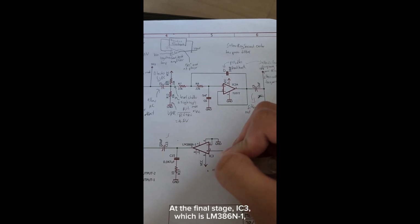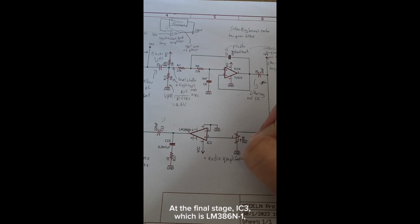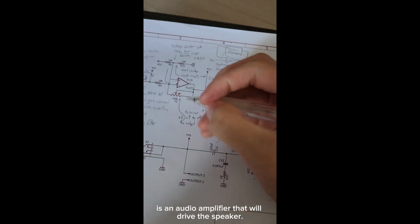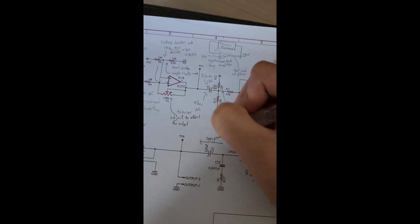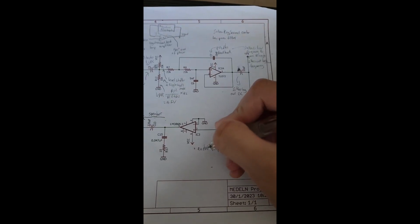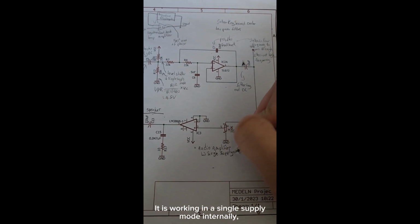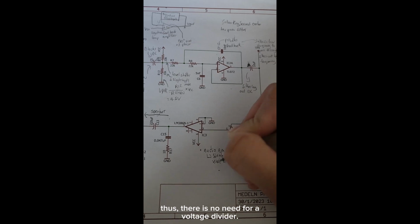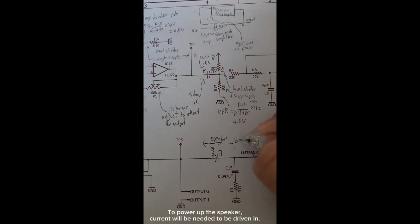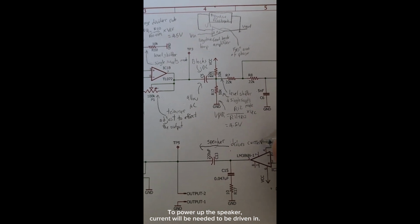At the final stage, IC3, which is LM386N-1, is an audio amplifier that will drive a speaker. It is working in a single supply mode internally. Thus, there is no need for a voltage divider. To power up the speaker, current will need to be driven in.